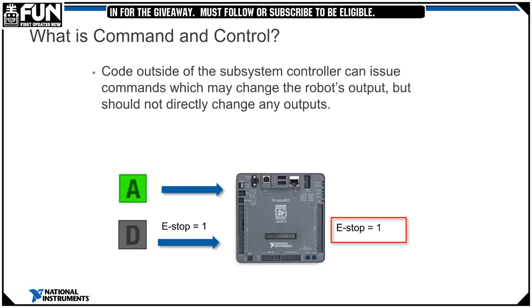For teleop, these same commands, go left, go right, pick it up, put it down, can execute asynchronously, which allows the robot to always be processing the latest driver inputs, and if implemented properly, new commands will interrupt, allowing the drive team to quickly respond to changing field conditions while also taking advantage of automated commands and command sequences.